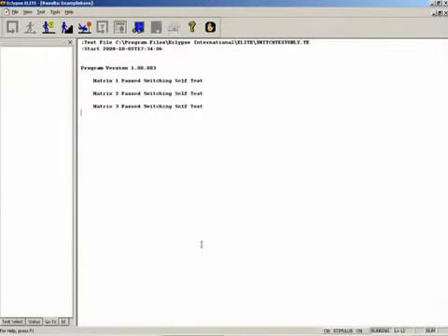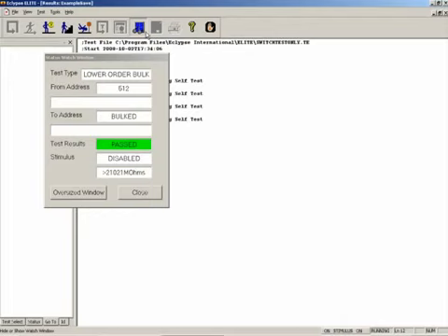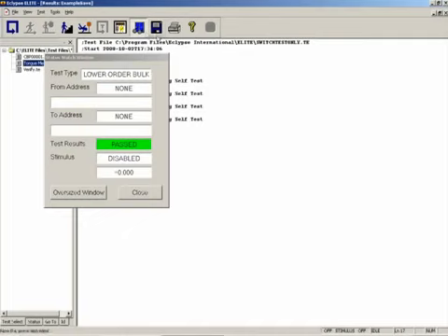The watch window displays the results of the current or last completed measurement. This information is updated as Elite is executing a test. The watch window displays the test points, the type of measurement, maximum and minimum values, test results, and current stimulus status. Continuous display of the measured value is likely to increase the time required to complete a test.